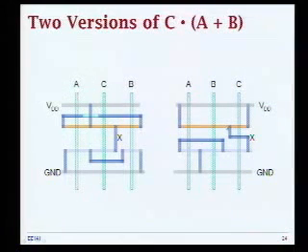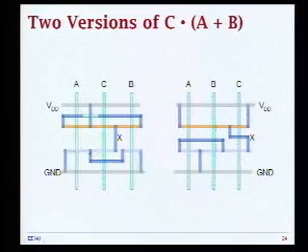Anyway, this is basically the case where this breaks, when you don't have a consistent Euler path for a certain combination. So you have to continue searching, as we did in the previous example, until you find a consistent Euler path such that you have uninterrupted diffusion strips over here. And yes, actually this is correct, because this is diffusion for the NMOS. PMOS is valid, NMOS is not.